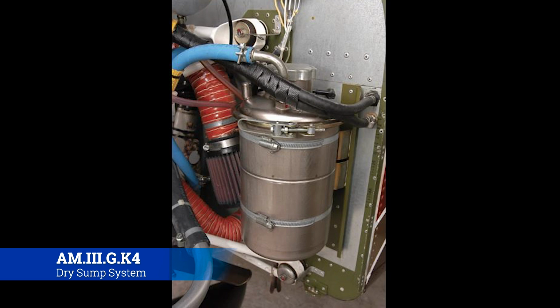Whereas if you change out the whole tank on an integrated wet sump system like the IO320, it's a significant ordeal, because you're taking off the bottom half of the engine. So you have little things like that to take into consideration. But those are the differences: wet sump, dry sump. A wet sump is on the engine. A dry sump is somewhere other than on the engine.